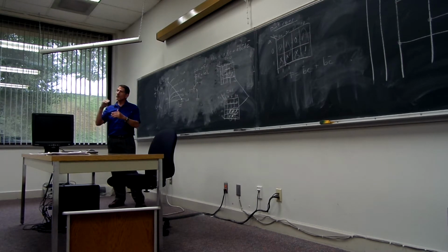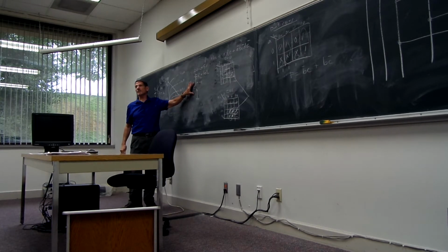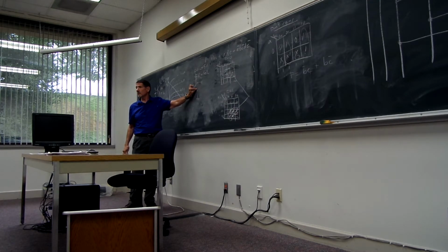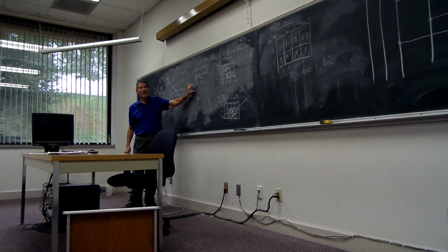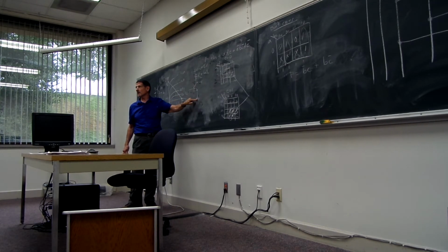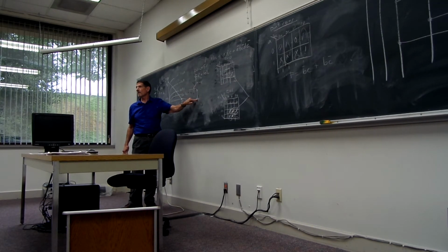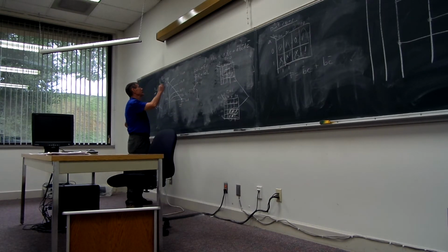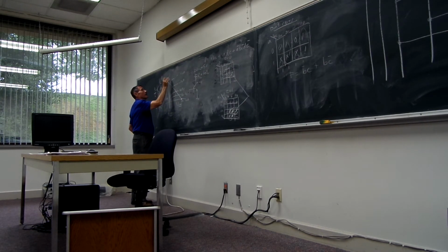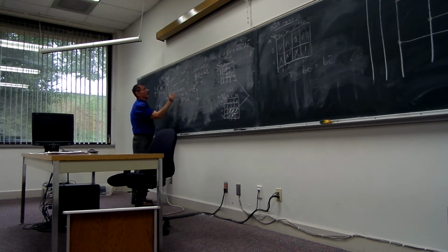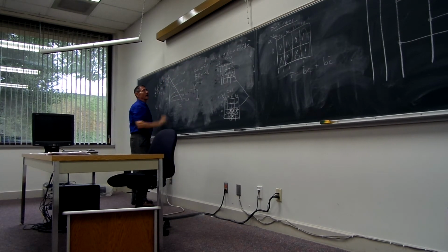If I drove so much current into the base that I saturate this thing and drive my collector-to-emitter voltage to 0, how much current is flowing? 5 volts here, 1 k resistor, no voltage between here and ground. How much current? 5 milliamps. So that would be my load line.